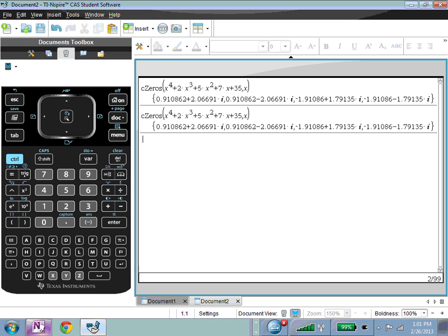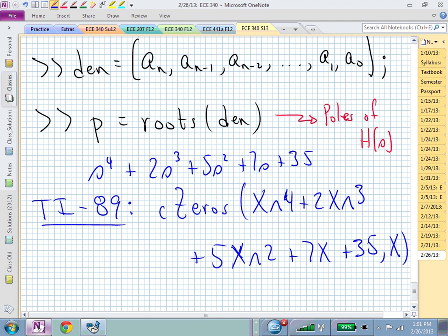Okay, so maybe I didn't make that point very clear. Now I was specifically restricting. The question was, well, didn't you just say that the coefficients had to be present and positive and then you would have stable roots? That only works for a quadratic, s squared plus something s plus something. For fourth order, third order, that's just a necessary condition, but it's not sufficient. Yes?